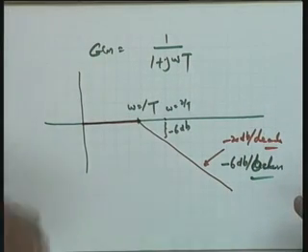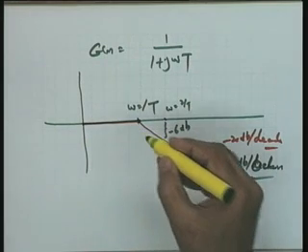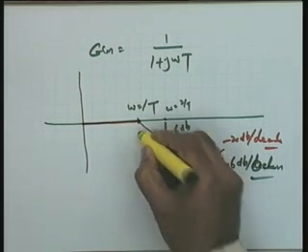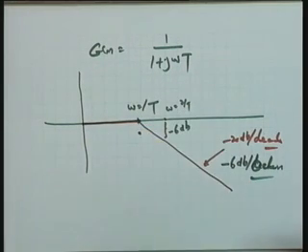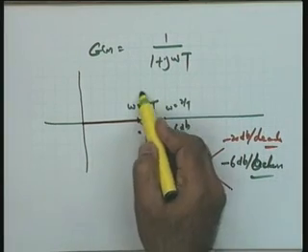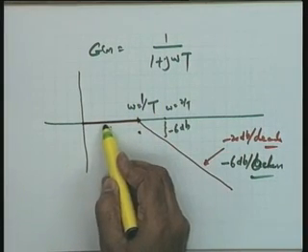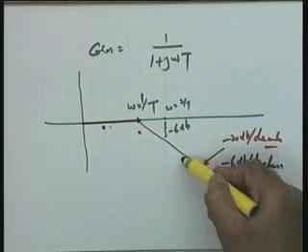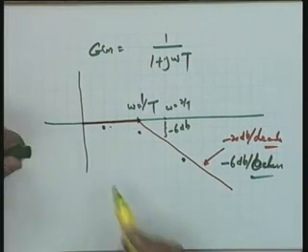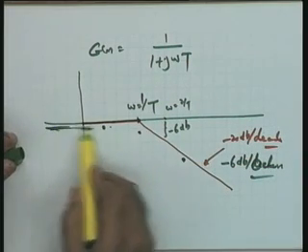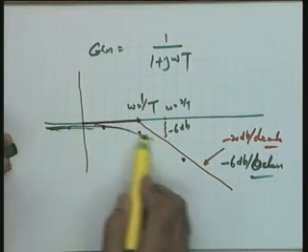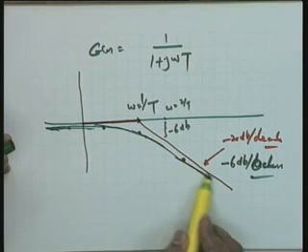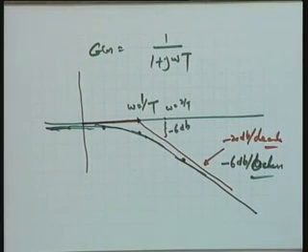Now from the asymptotic Bode plot, the actual plot will come in the following way. Just mark a point 3 dB down. Take 1 octave below, mark a point 1 dB down. Take 1 octave above, mark a point 1 dB down, and join these, making it asymptotic to the 0 dB line and asymptotic to the minus 20 dBs per decade line. This becomes your accurate Bode plot without any calculations.